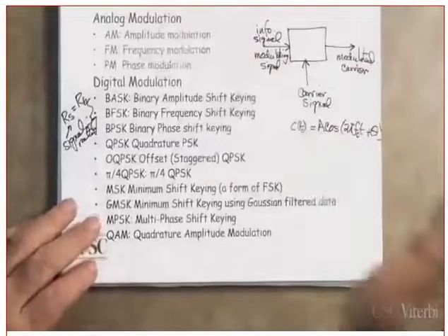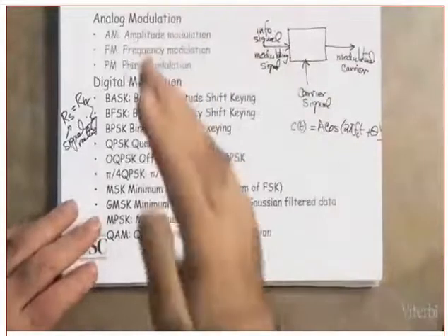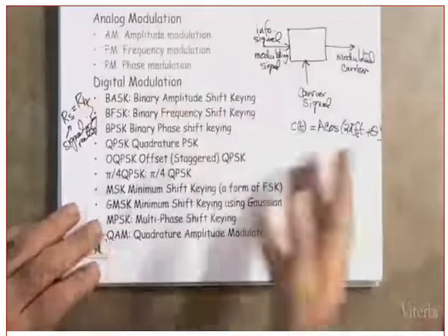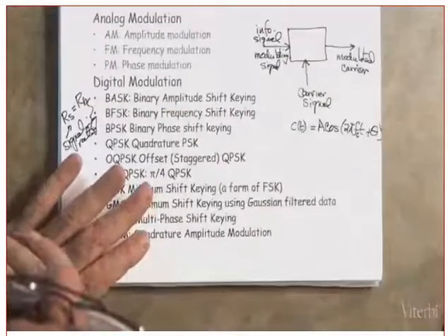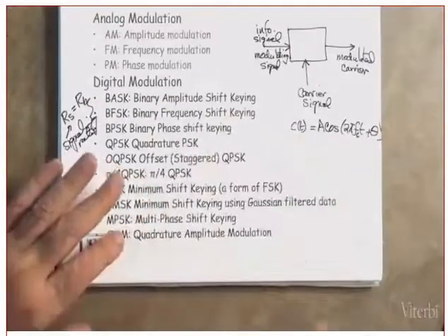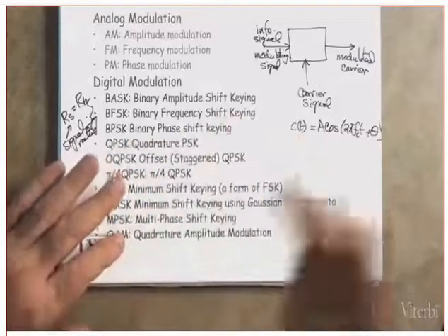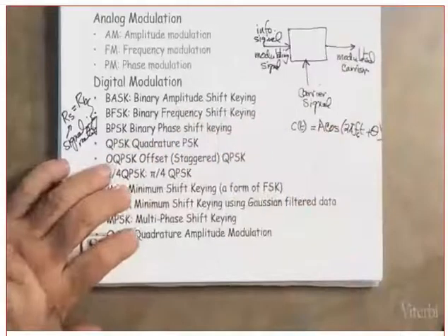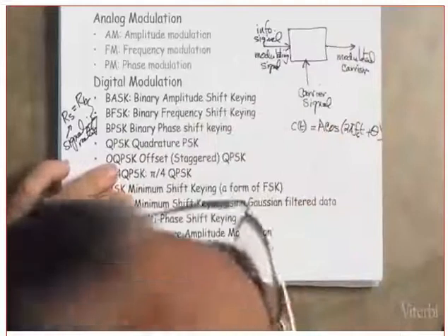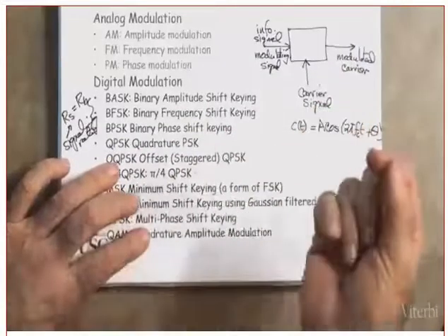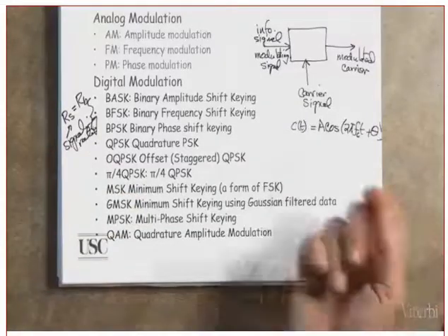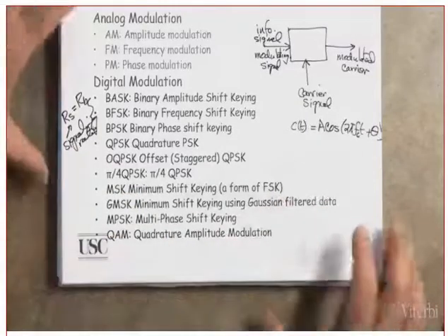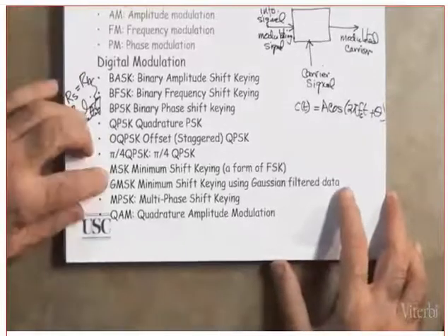The problem is what happens at the boundary between the symbols. Going from one symbol to another symbol, there could be a 180-degree phase shift. And when it is a 180-degree phase shift, what does it mean? It means you go from positive to negative or vice versa. Did you get this or not? During that time, we are in trouble. Clear? We are in trouble. Because when the amplitude reaches 0, what does it mean? It means the receiver will not have the ability to detect the signal. Will not have, because it's 0. Clear? Okay. But we'll get to that in a minute.